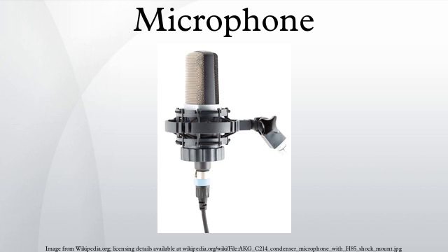Parabolic microphones have similar characteristics, but often have poorer bass response. Boundary or PZM. Several approaches have been developed for effectively using a microphone in less than ideal acoustic spaces, which often suffer from excessive reflections from one or more of the surfaces that make up the space. If the microphone is placed in, or very close to, one of these boundaries, the reflections from that surface are not sensed by the microphone.